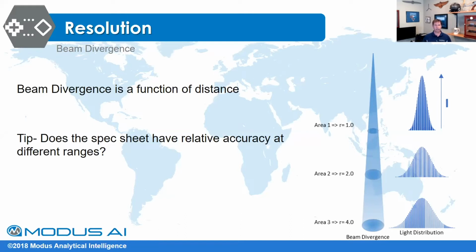So this is a specific item in a spec sheet that you're going to see. And so when you're looking at, let's say, a Velodyne, or you're looking at a Riegl system, and they're quoting these accuracies, they are relative, because you're going to need an IMU or a GNSS and an IMU to actually give that absolute accuracy, which we'll talk about in a minute.